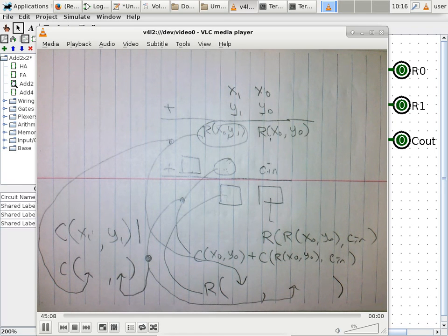Okay. The complexity is coming from the fact that we have tons of terms here to make up this, but they are all computing at the same time. So the propagational delay to get the actual result is no more than just 3 levels of gates, regardless of the actual width of your adder.